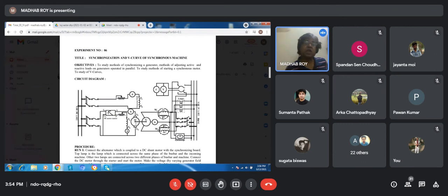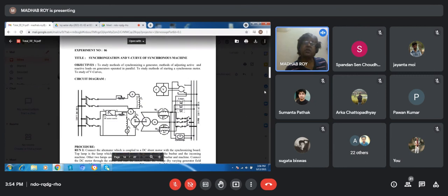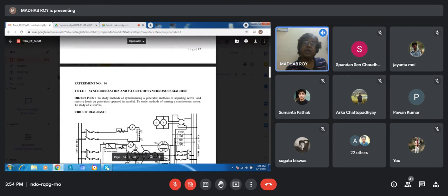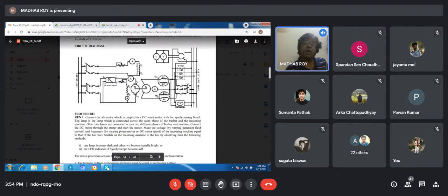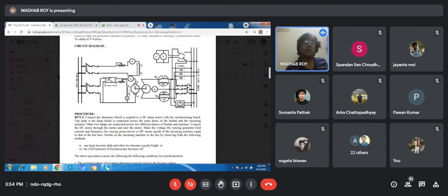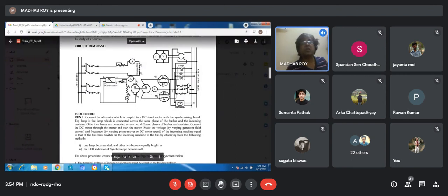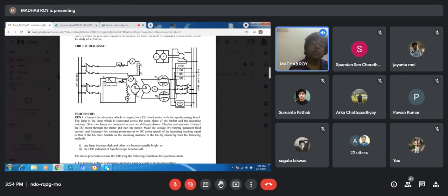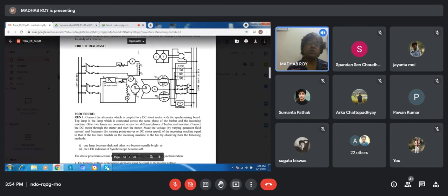Again, this shunt motor can be run as a generator, and you can see that at a very reduced amount of generator action, this 2 wattmeter reading as well as this ammeter reading will be very high. So this is the final reading we have to take. And another point is that at a certain amount of power, if we further increase the power, when we are trying to take out power from this three-phase system through the DC generator, then what will happen? This synchronous reluctance motor will be out of step. Do you know what is out of step?